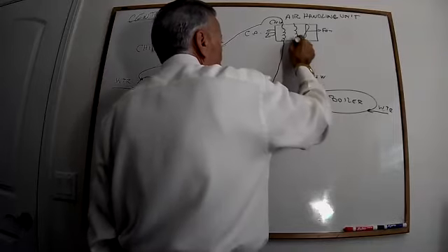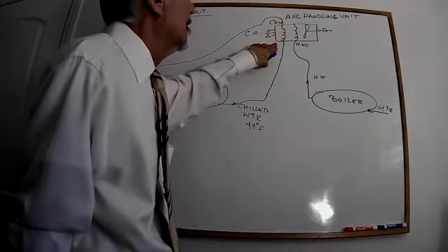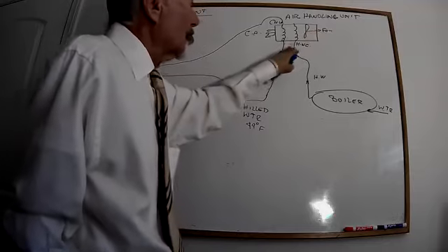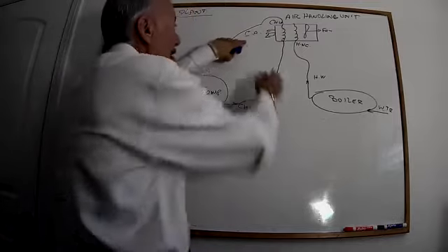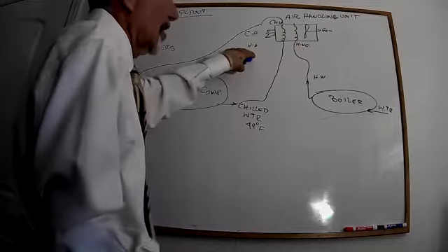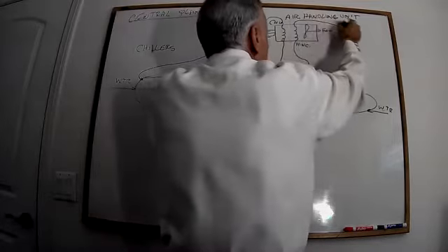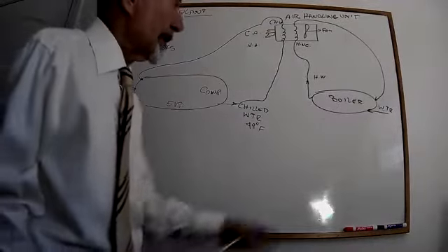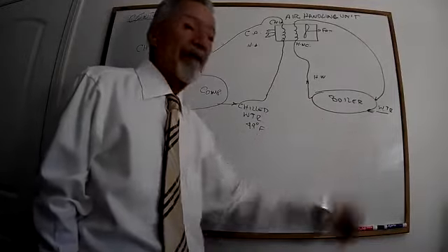And that goes to this coil. During the winter time, the chilled coil is off by the thermostat. This fan will work, go through this hot water coil, and you have hot air this time coming out to the classroom. And whatever is left over comes back to the boiler. That's another loop that we create. So it just keeps circulating, so we don't use this water from outside anymore.